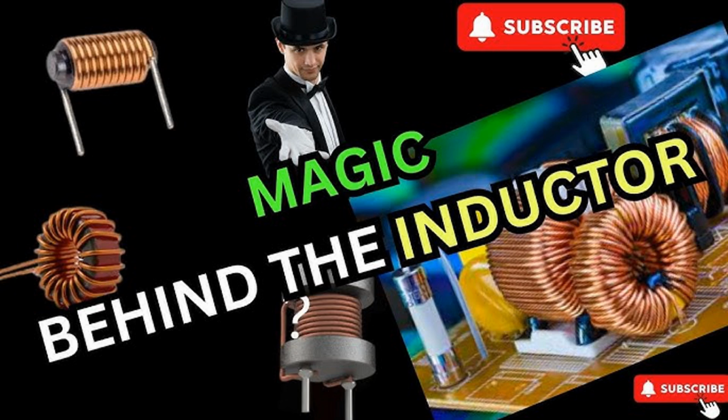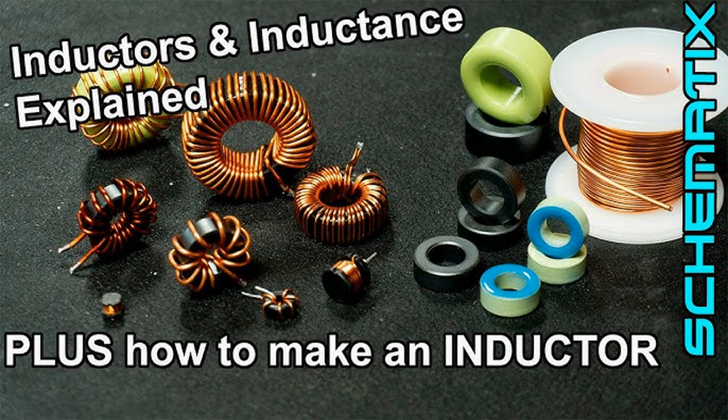Applications of filtering with inductors. Power supply filtering. Application. Inductors are used in power supply circuits to filter out high-frequency noise or ripples from the output. This helps ensure a smooth DC voltage is delivered to sensitive electronic components. Example. In a regulated DC power supply, an inductor in conjunction with a capacitor can form an LC filter to reduce the ripple voltage after rectification.